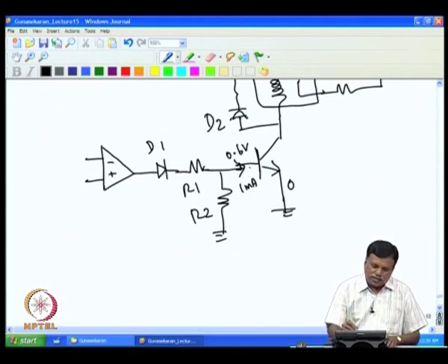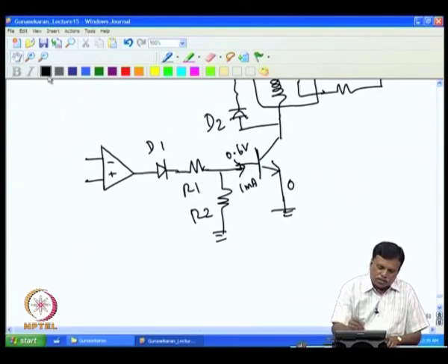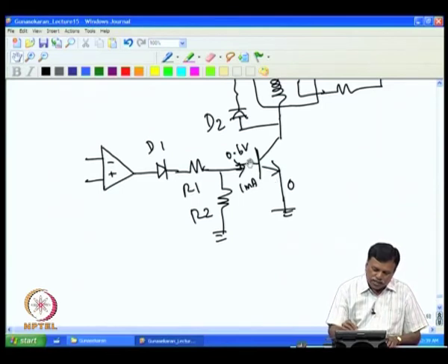When the voltage goes minus, this becomes 0, but then the storage charge in the transistor, that is the base emitter capacitance, has to be discharged, and for that only we are using R2. So, R2 can be large, there is no problem, because if this is a few pF capacitor, taking R2 say for example 10K makes the discharge time only a few nanoseconds.